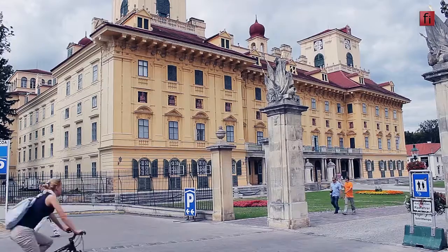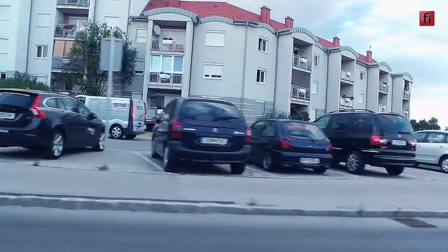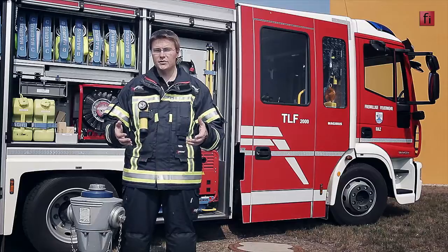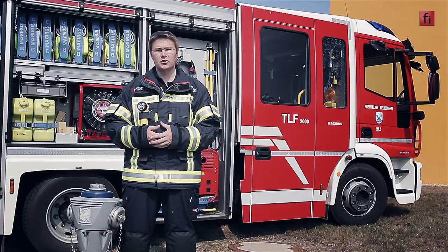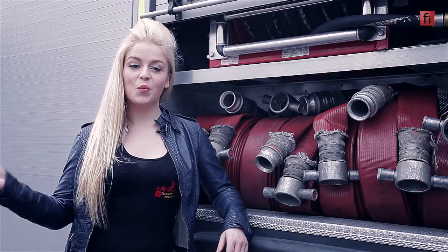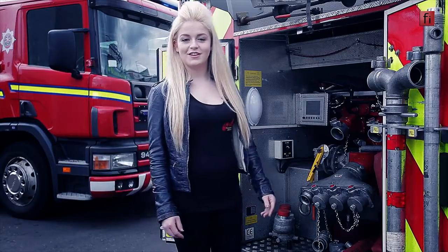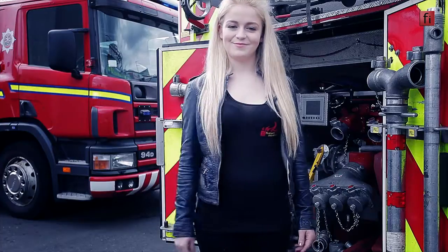There are certainly historical buildings, industrial buildings or other buildings that deserve protection in your region. For most of these, there might be a required minimum discharge flow for hydrants. The question is, what's the maximum discharge flow of the hydrants in your area? But how should we meter the flow of a hydrant? Here we have two possibilities.